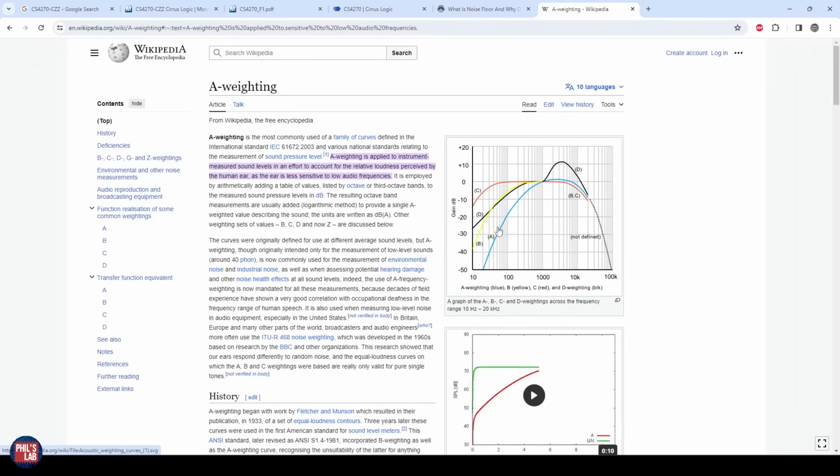audio measurements. And effectively, these are weighting curves. You can kind of think of them as customized frequency responses that are multiplied with whatever measurement you're doing. And this is typically applied to audio equipment. And you'll see sometimes on websites people stating noise floor with and without A-weighting or THD with and without A-weighting and so on. Because, for example, the A-weighting, which is in this Wikipedia graph, this blue curve on the right graph, you can see that attenuates more lower frequencies. Then we have this fairly narrow passband, and we're attenuating some of the higher frequencies up to 20 kHz.